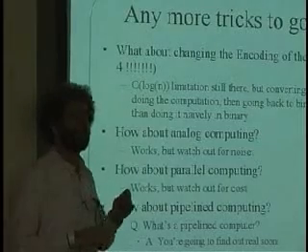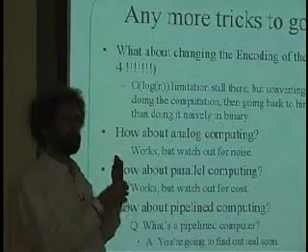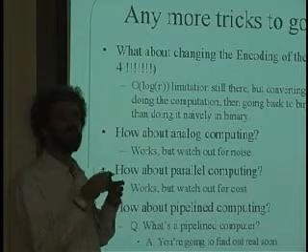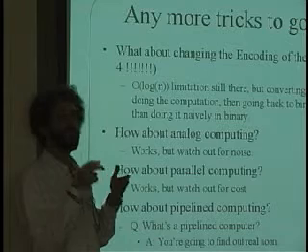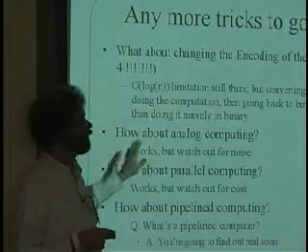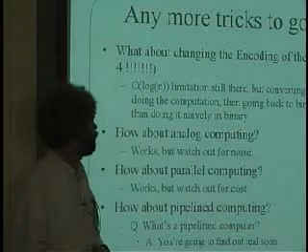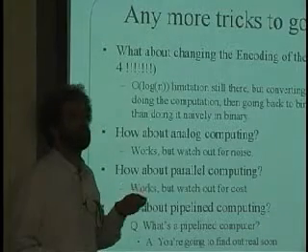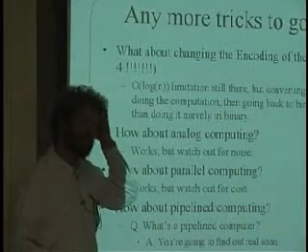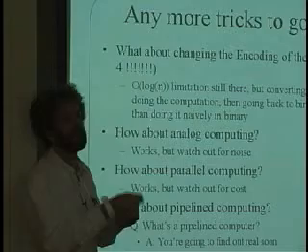It turns out that you could actually encode more possibilities in a voltage range. So you could, for instance, say 0 volts is a 0, 1 volt is a 1, 2 volts is a 2, and 3 volts is a 3. And every wire can now take 2 bits of data, being a number between 0 and 3. And you can do more and more of that to, in the limit, having what's called an analog computer. There you don't have any digital system at all, but you have just a voltage meaning what the number is. And to add 2 voltages to each other, you use an amplifier, what's called a summing amplifier or an op-amp, and you sum the voltages and you get a sum out.